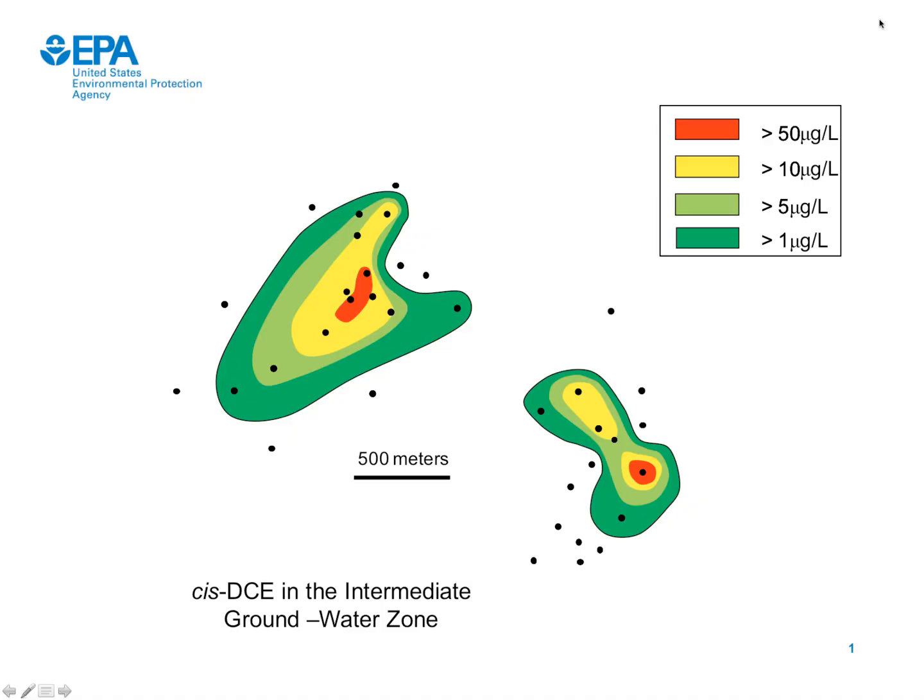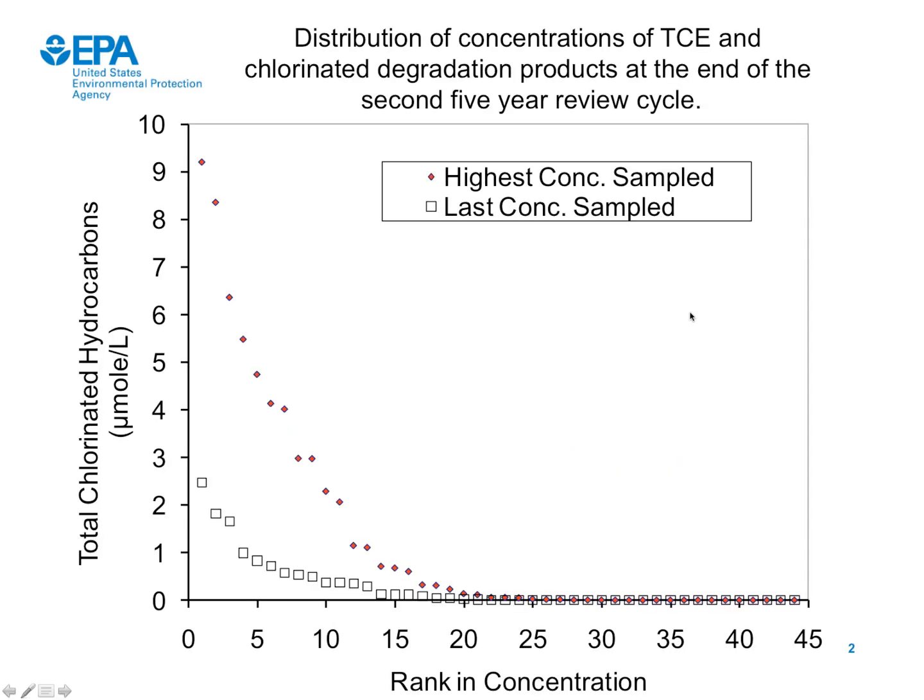Many of our sites are what I call bullseye sites, where there's no general consistent direction of groundwater flow. And so the plumes that form are irregular and almost stochastic. So you have a highly concentrated center of contamination surrounded by a periphery of gradually diminishing concentrations in any direction. These plumes are hard to monitor, and they're hard to interpret. Next slide.